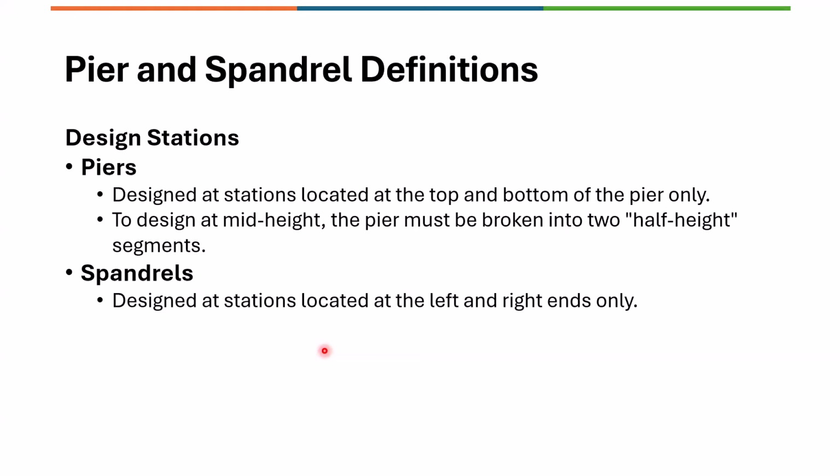So in case of the out of plane bending or the other aspects related to the analysis like P delta analysis, you can consider the out of plane bending, and if that is needed, you will have to break the wall at mid height, and you can also label them so that if significant bending moment is expected at the mid height, then the pier label will give outputs only at the top and bottom of the pier label, whether it is an unmeshed wall or a label assigned to a group of shell elements.